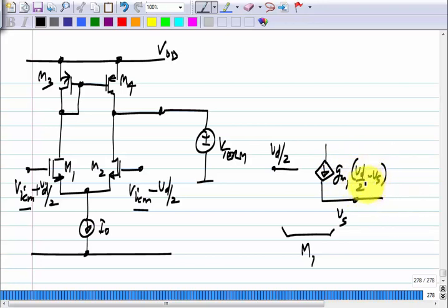Actually, this is very important. I see a lot of you writing the current source symbol without writing anything next to it. Okay. If you are very comfortable with circuits, these things will work. But if you are making mistakes, just be systematic. Draw every transistor, the quantity corresponding to each of the controlled current source and so on. Also, there is always this tendency of somehow assuming that the source is at ground and writing GM times the gate voltage and things like that. So, just be systematic and do it, because this is the first step. If you make a mistake here, you cannot get the right answer.